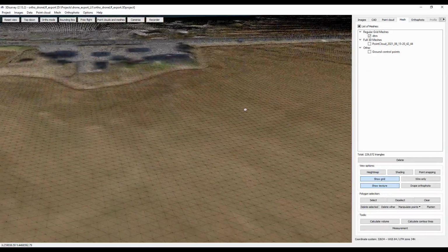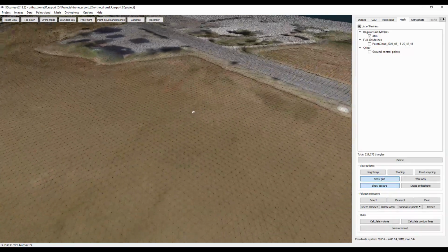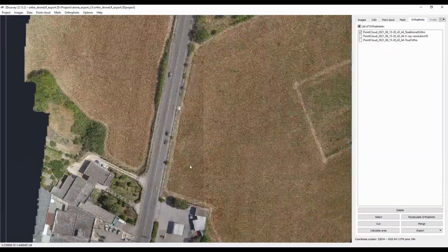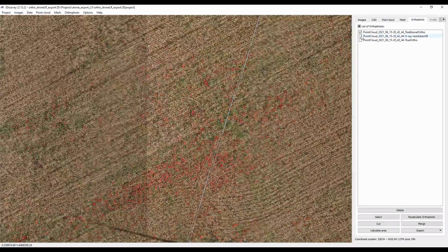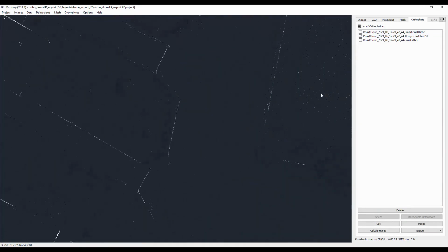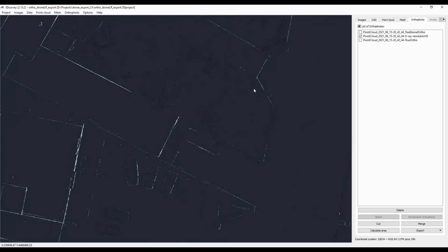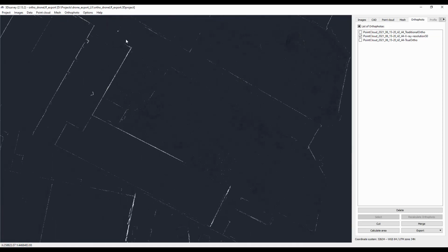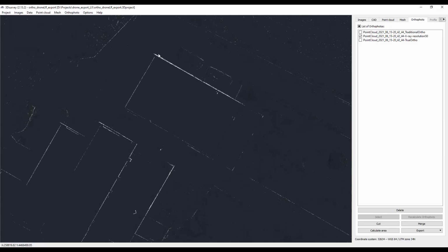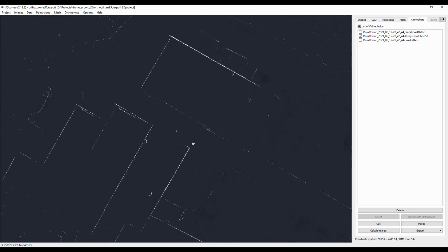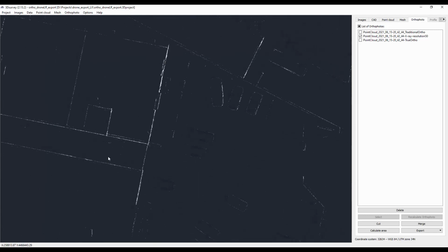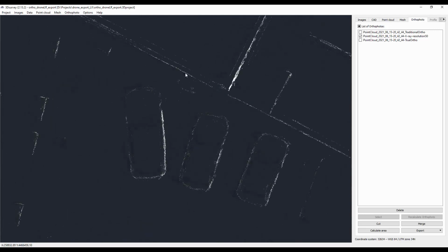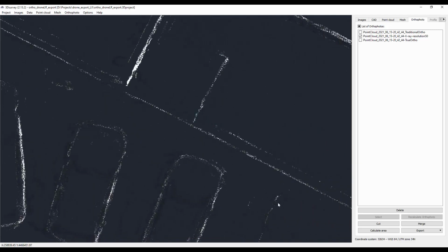We also made a digital terrain model for this area and of course an orthophoto map. So we have traditional orthophoto, we have an X-ray image. This one can also be exported to AutoCAD using the same workflow, and this one will help to extract the outlines of the buildings, for example, or maybe to draw these walls here or something like that.